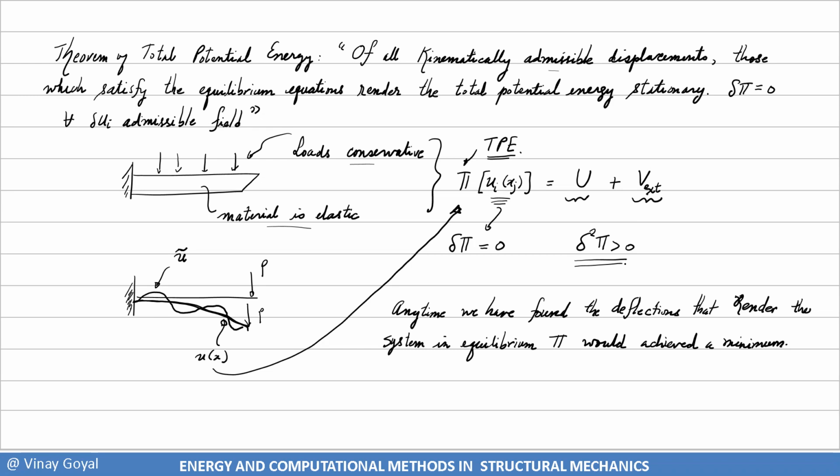So say you have a linear elastic material. For the most general linear elastic material, fully anisotropic with 21 independent constants, sigma_ij equals C_ijkl epsilon_kl.